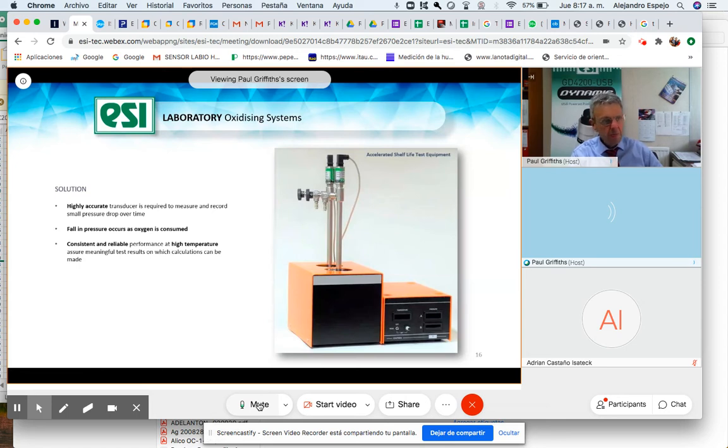So normally, the full-scale output would be 100 millivolts, but they needed 47 millivolts. So again, it's a customization. It's very easy for us to do that. We just fit a resistor network to the sensor, and we reduce the output. Most people want the highest possible output. This customer wanted a specific output.